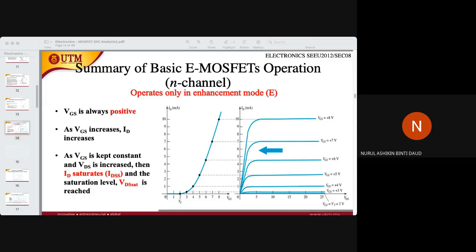From here, you can also find the value of VD. So VGS is equal to VT. You will notice this for different reference books. And ID on is not always the same as VT or VGS threshold. ID on can be at any value of VGS. But VGS threshold is always the value at which the drain current starts, when the device turns on. So please note this as well.